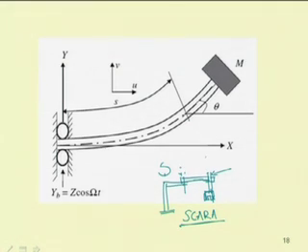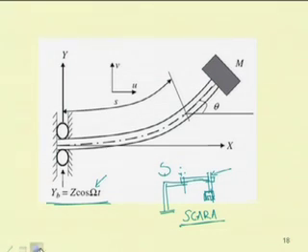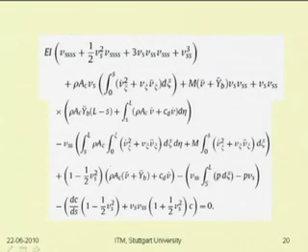If you consider a prismatic motion in this cantilever beam, then you have one additional base excited term, that is Yb equal to z cos omega t, in which omega is the frequency of this oscillation and z is the amplitude of this response. So, instead of taking a small response, if one considers a moderately large response, then the equation can be written in this form.